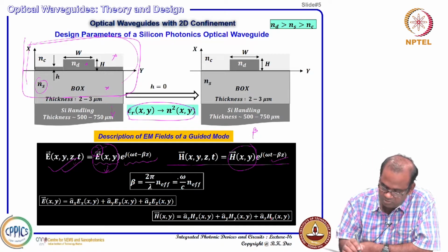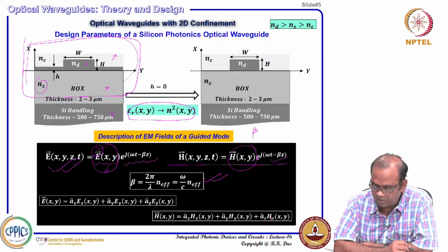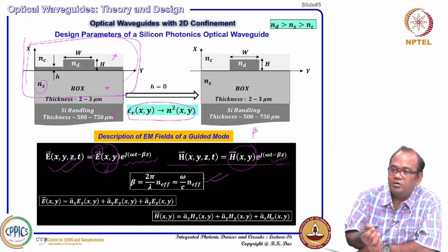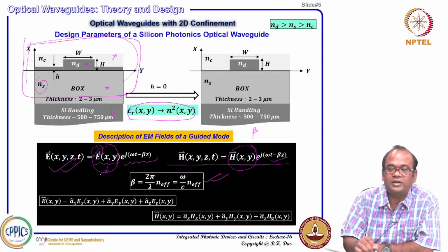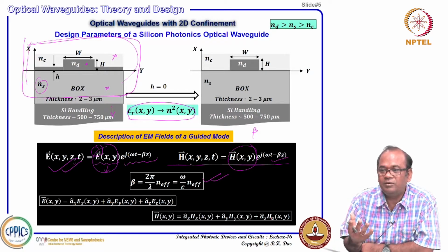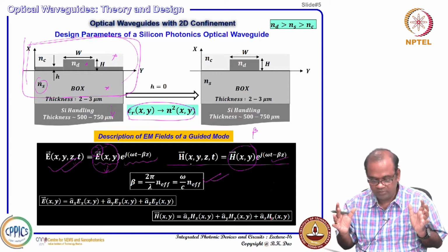Okay. So, beta will eventually be obtained like this. It can happen that, like whatever you saw in your 1D waveguide, you can have multiple solutions for n effective or beta and multiple sets of these vectors, and they are actually the guided modes or confined modes, you can say. Those types of solutions we have to accept.